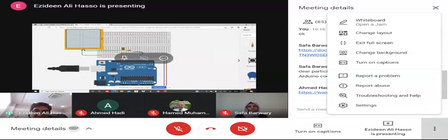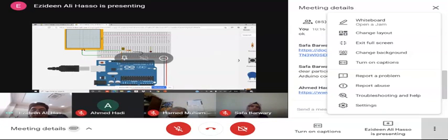And from here, the breadboard, let me explain the breadboard as well. All these points in this row, from here all the way to here, are all connected together, okay? Same thing on the other side. From here up to here, they are connected together. And the one next to them, they are all the same point, okay? But of course, this column and that column are different, okay?